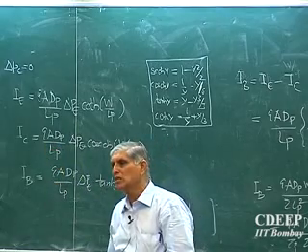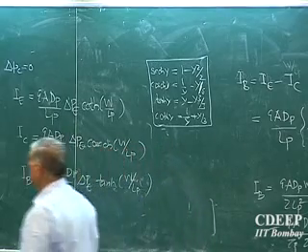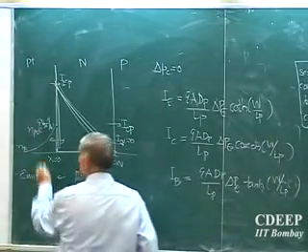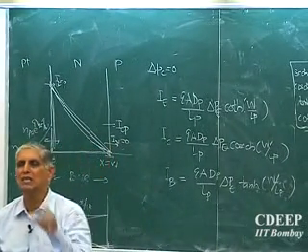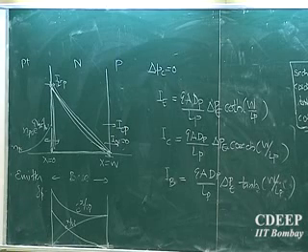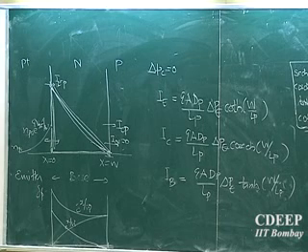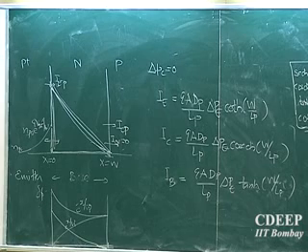Why minus 5, minus 10 volt? What is the value of VB? Across it, how much voltage is there? In forward bias, how much maximum voltage do you get? At best EG. At best EG. Okay. That is heavy doping. Okay, and by then it will become intrinsic. So essentially delta VB is at best 0.6 to 0.8 volts. Is that correct? VB varies from 0.65 cut-in, or 0.6 minimum you can say, to 0.8 volts.